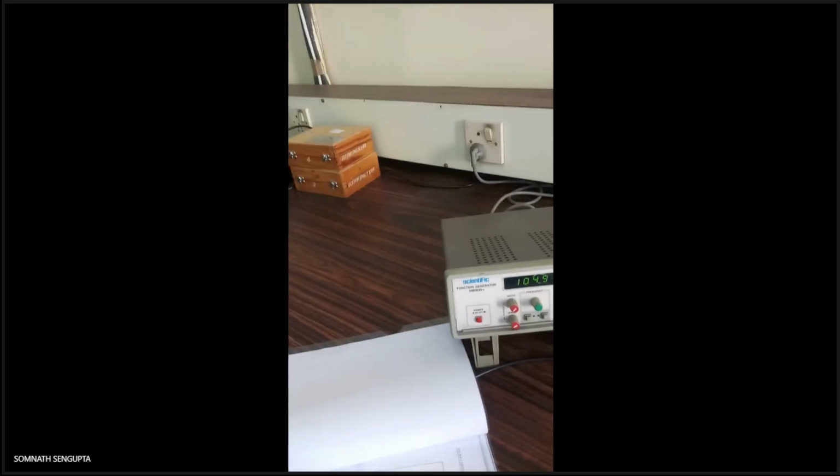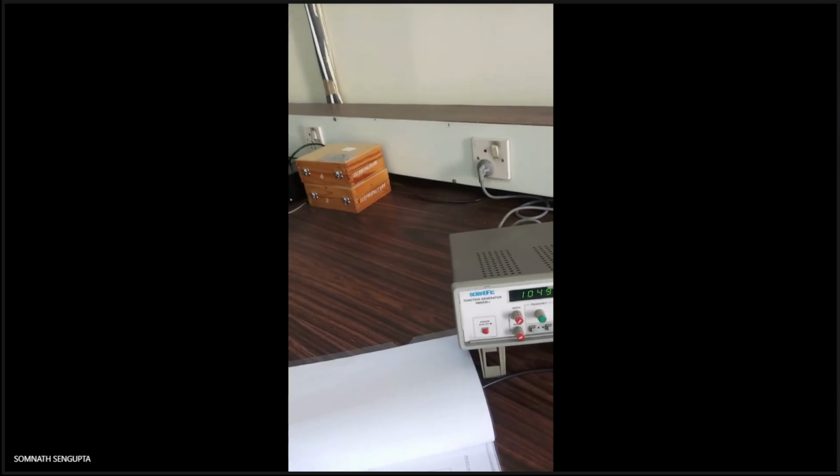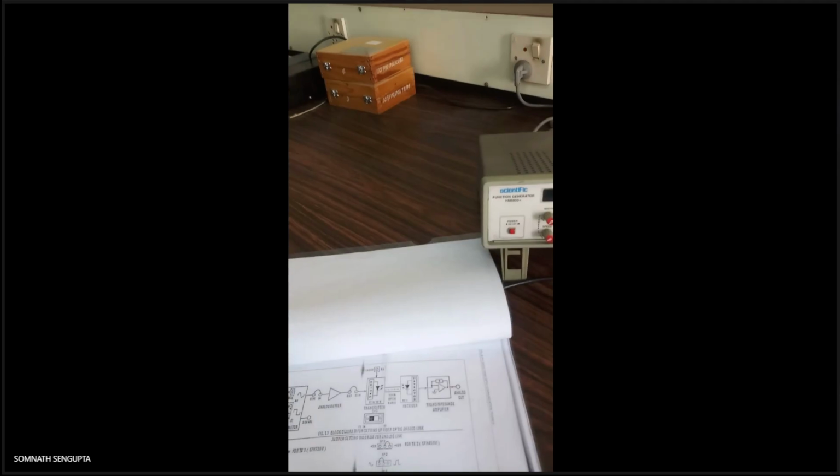Okay. So now the output has a load resistance, and the current is actually very low because it depends on the number of photons incident. So the current is very weak in nature, and along with that many types of internal noises are present in the photodetector.